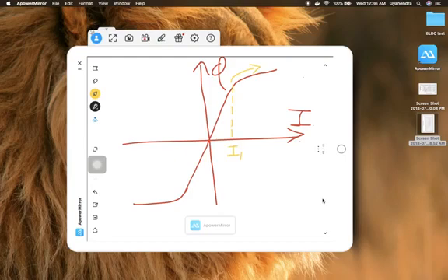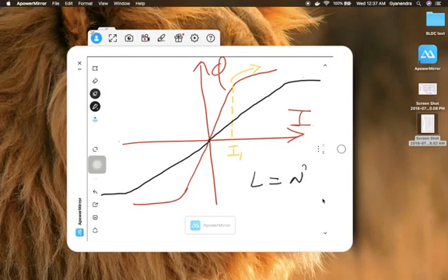So that's a problem without having an air gap. So what happens if you introduce an air gap? The slope of the phi-I characteristic reduces, and it goes like this. That means inductance has reduced. If inductance has reduced, we already know that L is equal to N squared by R, which means reluctance has increased. So the black one is representing what it will be with air gap.